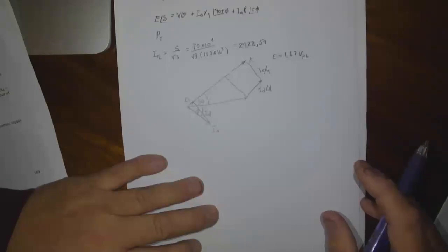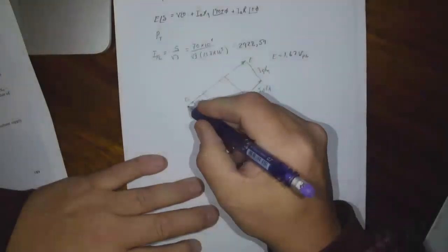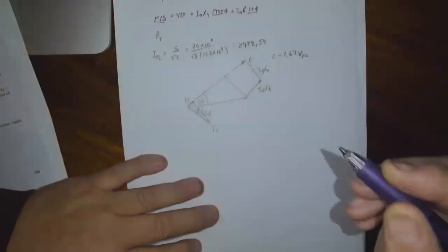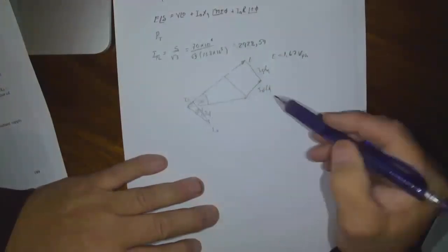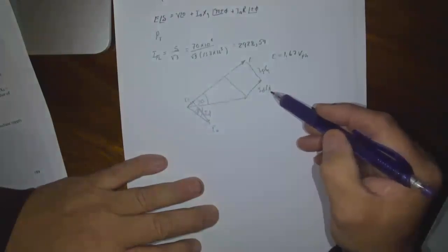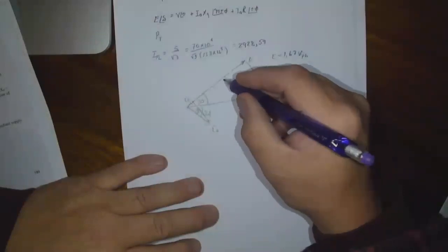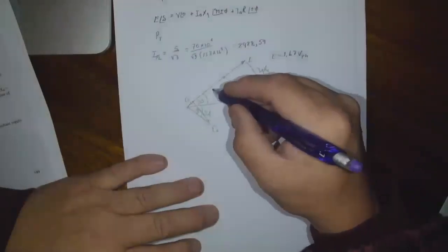You see on that phasor, which is the armature current phasor, what is the current which is in phase with it? Is it not IQ? No, remember IQ lies there. ID lies there. Okay, all right. So now ID XD must lead this voltage. This voltage leads this current. All right, so now we can calculate this part here.